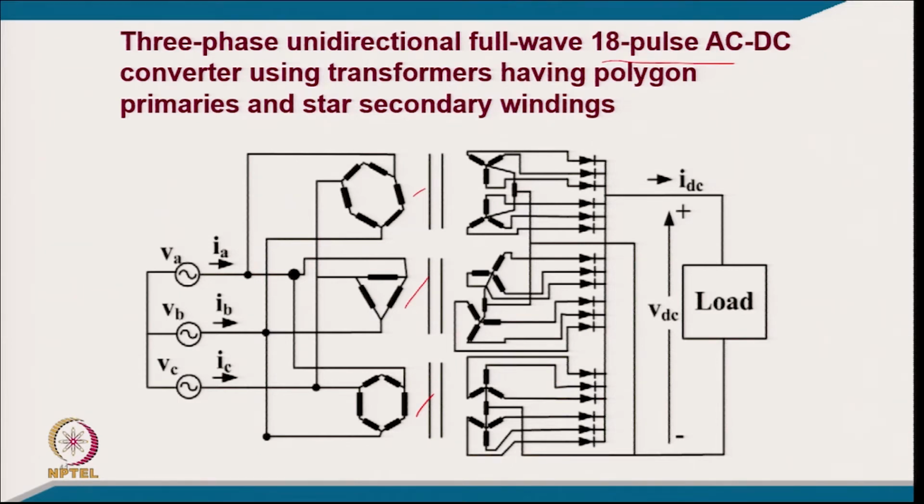So you are getting a phase shift of 20 degrees from one phase to another consecutively, and you are able to use the 18 phase supply for an 18 pulse converter with 18 diodes, and you will get 18 pulse in the output. Of course, in the input you will get harmonic orders of 18 plus minus 1, so the 17th will be the lowest harmonic. That will improve the power quality on the input as well as the number of pulses increased in the output.